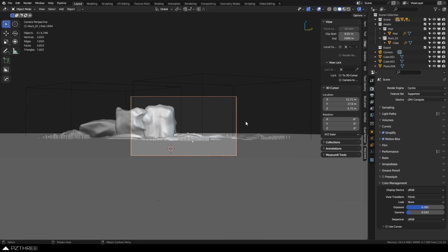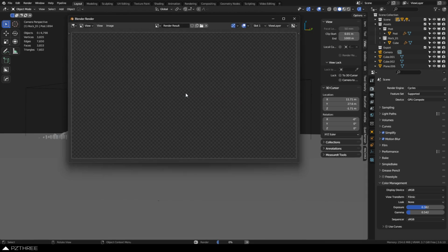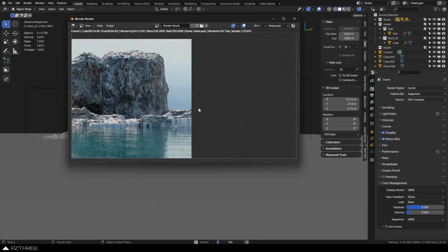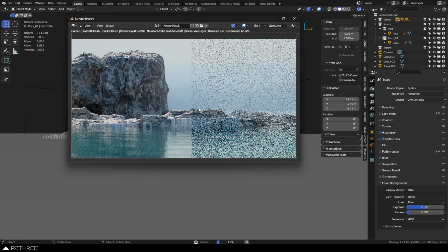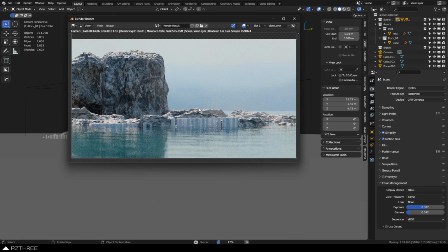It doesn't change the results too dramatically, I would say, but it can speed up your renders quite a bit if you lower the quality, obviously, or use fast global illumination. I usually just use the drop downs like lower memory usage, and then let's do limited global illumination or fast GI, and usually that'll speed you up as well. I don't know if I had those on for this scene or not, but usually it speeds it up a bit. And it virtually looks almost identical, but you could do tests and compare and all that.